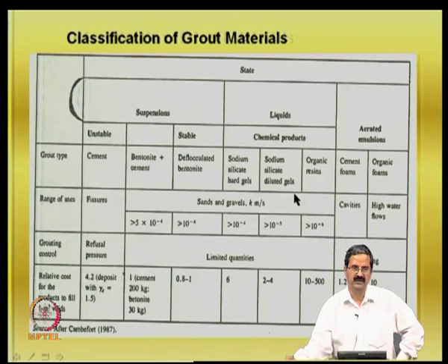Essentially, you should take an undisturbed sample of the soil, the material, and then you are looking for strength improvement and permeability reduction. There are different chemical products here, and depending on whichever gives the best performance according to our criteria, one can choose and then use it in the field with an adequate margin of safety.